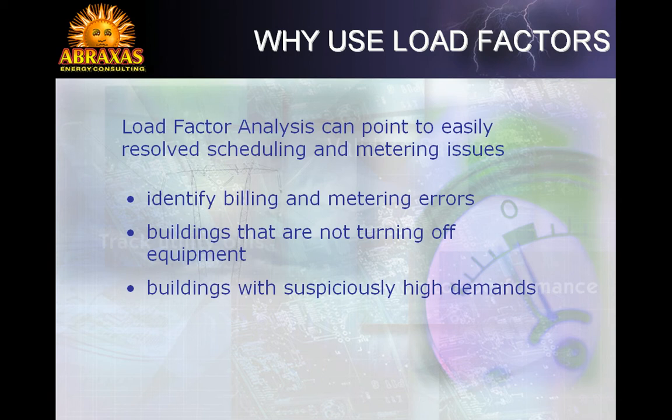Also, many things contribute to a particular building's load factor. A building left on 24 hours can still have a low load factor if there are large peaks each month. For example, a 20-bed hospital that has a scheduled MRI truck visit each month. The MRI demand is large and can greatly impact the load factor of a small facility.